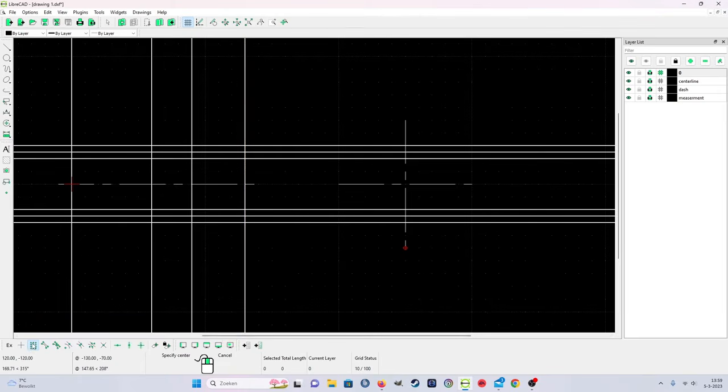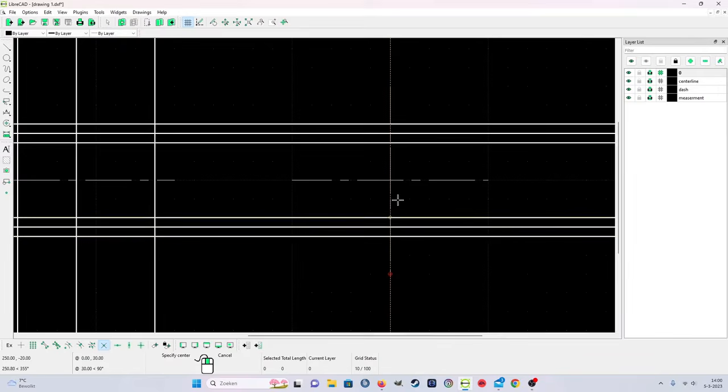And then in this case I can use the grid, but often, as I explained, you must zoom very far in to get it on the line exactly. So I put the grid off, and I'm going to use the snap intersection. So I put the snap on, the grid off, and I select this one. And what it does, it snaps intersections.